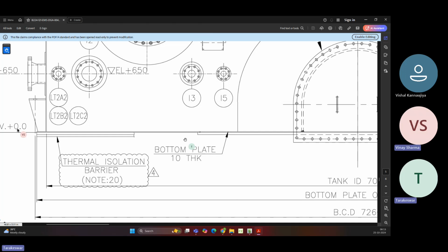That is saddle support, right? Yes, that is saddle support. In that case, you can't put it in air. That saddle support you need to provide, and below that saddle support you need to make that foundation, because the whole load will go to that saddle support. Okay. Next.